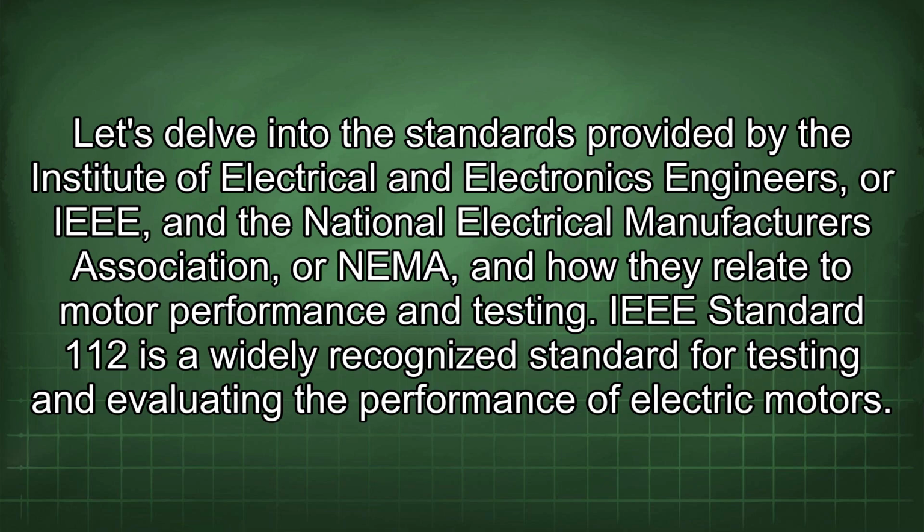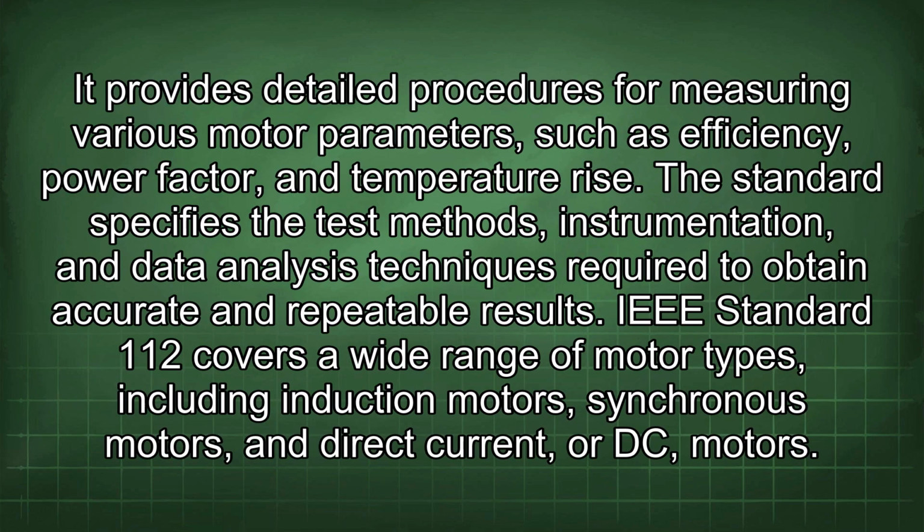Let's delve into the standards provided by the Institute of Electrical and Electronics Engineers, or IEEE, and the National Electrical Manufacturers Association, or NEMA, and how they relate to motor performance and testing. IEEE Standard 112 is a widely recognized standard for testing and evaluating the performance of electric motors. It provides detailed procedures for measuring various motor parameters such as efficiency, power factor, and temperature rise. The standard specifies the test methods, instrumentation, and data analysis techniques required to obtain accurate and repeatable results.